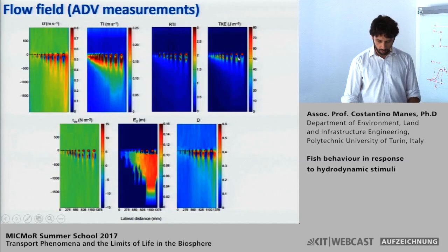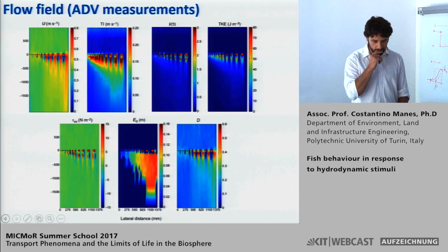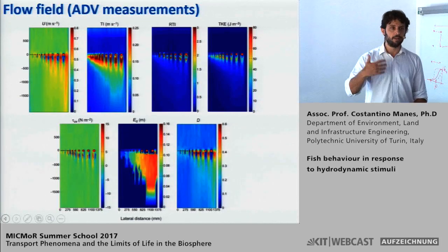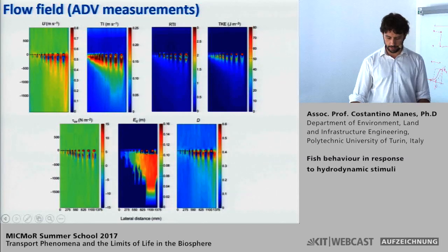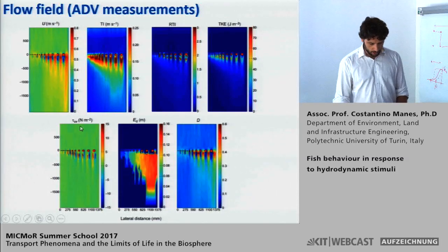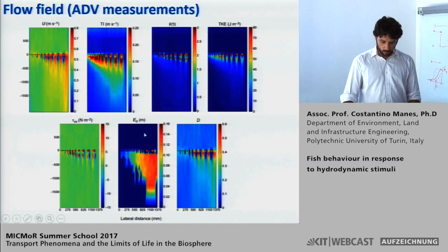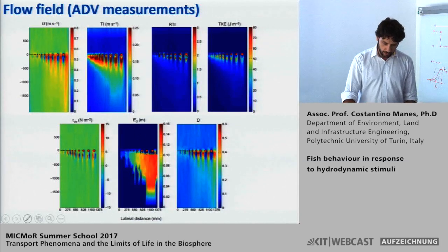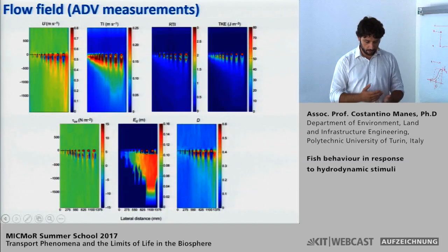We have chosen to address these turbulence metrics because these are those that were investigated in the past literature. So saying the turbulent shear stress, this is the eddy size that we have been estimating using two-point correlations. We didn't trust the Taylor hypothesis